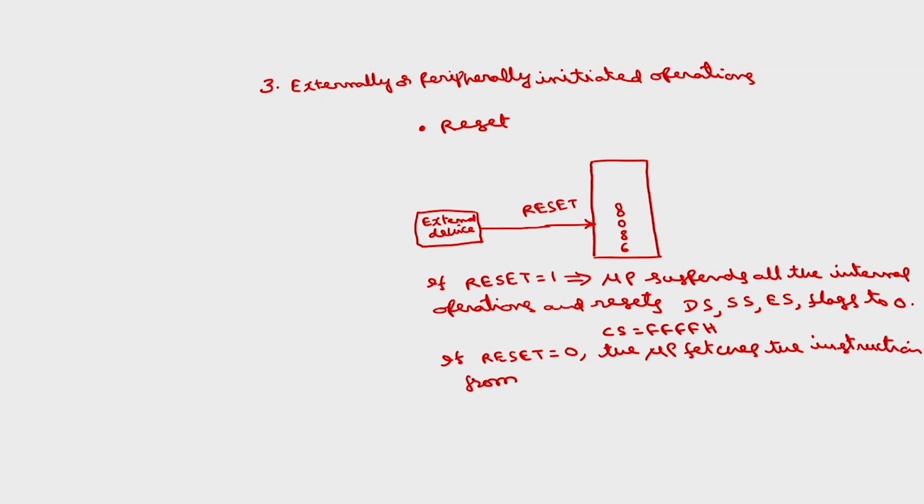We know that the physical address of any location is given by code segment contents into 10H plus instruction pointer.